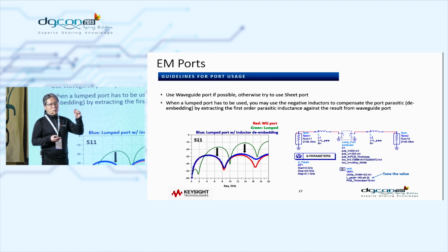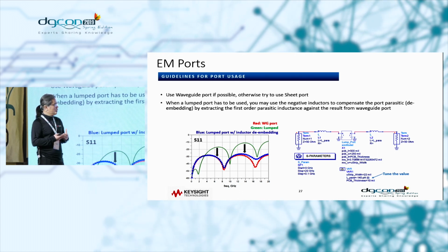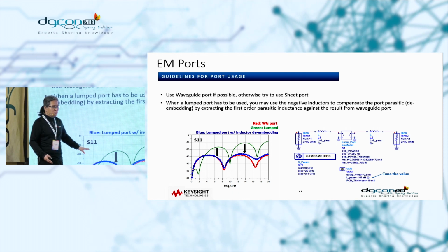Once you know it, you can use this value whenever you simulate, because that will represent the port parasitics with certain PCB structures, so that will help to increase the accuracy of the simulation.